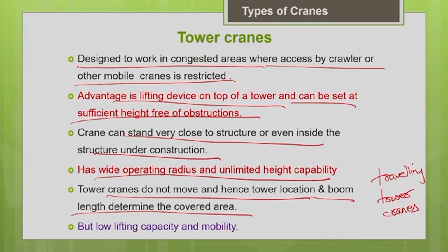In certain project sites where you need the mobility of a tower crane to various locations within your site, they prefer to have the rail track laid, and we can have the tower crane moving over the rail track. Sometimes the cost of erection and dismantling of the tower crane is very high when compared to the cost of the rail track. So in that case they go for the rail mounted tower crane, so that they can reduce the cost of erection and dismantling.